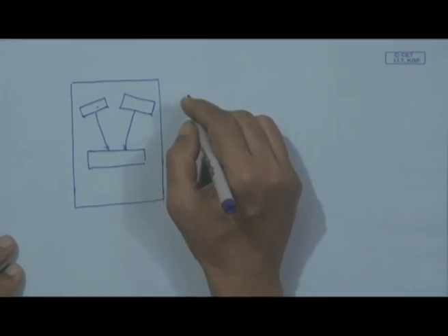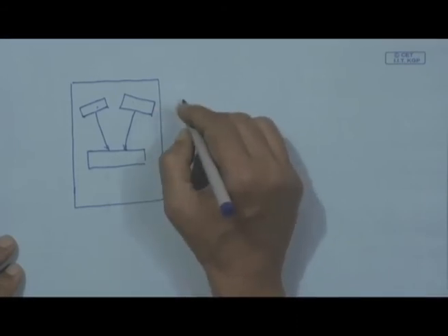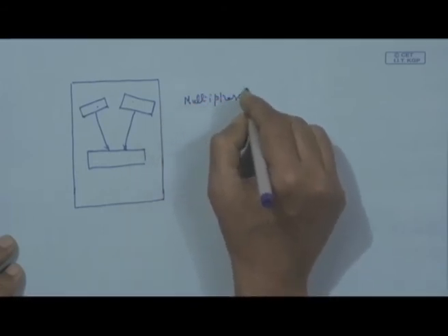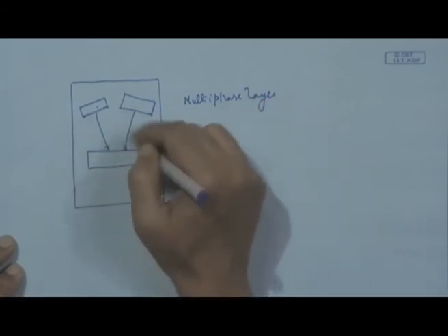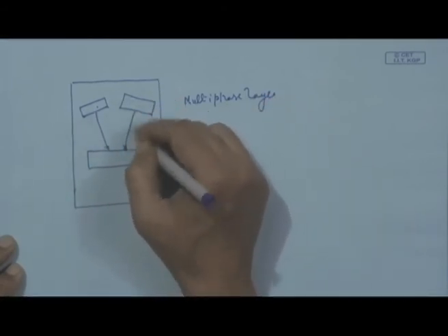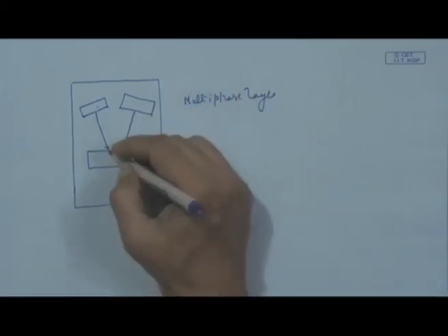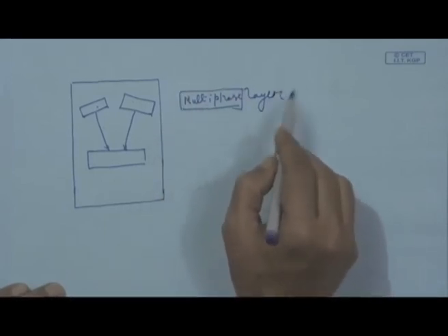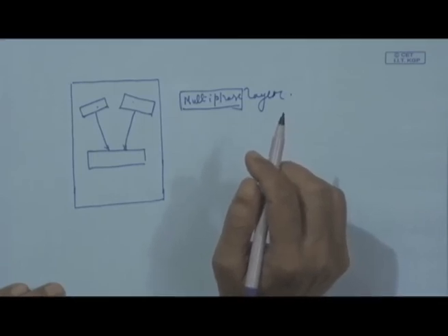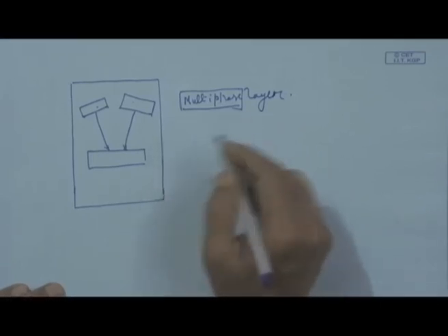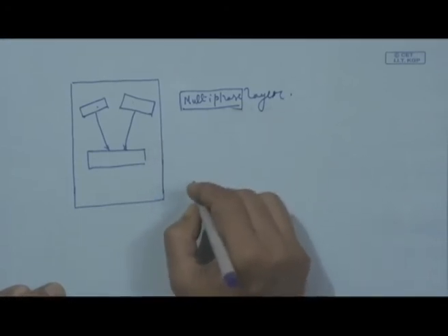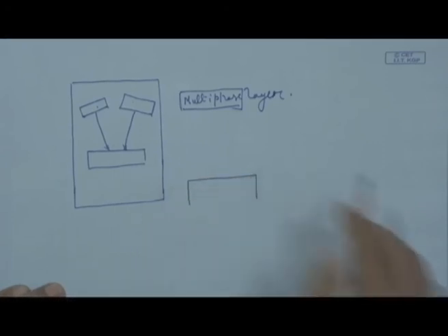By this multi targeting we can have, instead of a monophase, a multiphase layer. That means both are ejecting material, so both will form an alloy. So, it is not a monophase, it becomes a multiphase single layer, but it can also be a monophase multilayer, that means it can be interrupted.